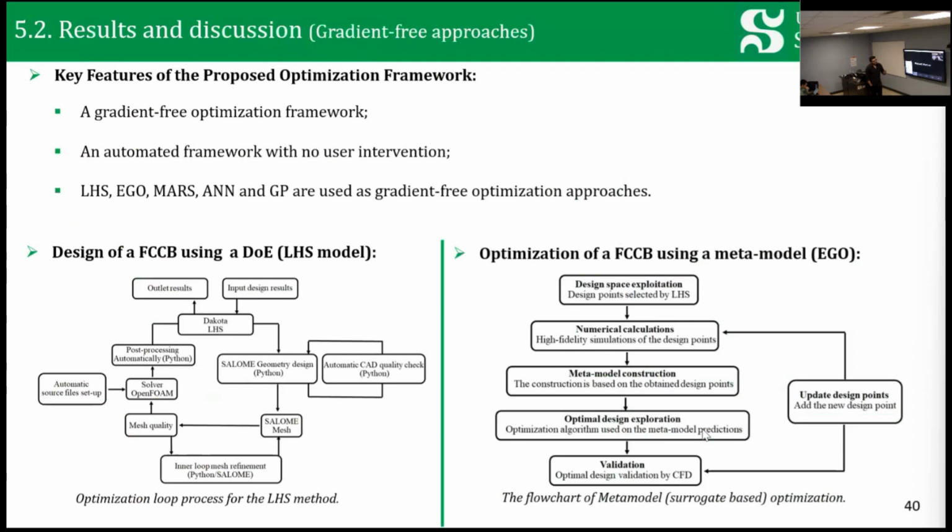This framework also works automatically without user intervention, and we use LHS as the design of experiments and some metamodels to find the efficient blower. It starts with importing the data of design variables and their bounds into Dakota, and Dakota employs LHS in order to create different samples.